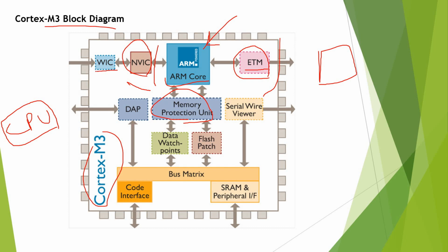Now we have another optional block, which is the wake up interrupt controller. As we saw before, the Cortex-M is a low power efficient processor. This means that to have an optimal application running on it, we need to have our application running most of the time in low power mode. Cortex-M3 has two really low power modes, sleep and deep sleep mode. For deep sleep mode, which offers the optimal power consumption, a lot of features and functionality will be cut off and will not be available.